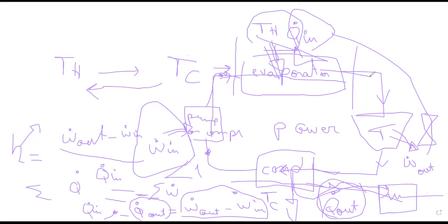And then, after passing by the expansion valve, when it goes through the condenser, it will reject heat to a medium of lower temperature. So I forced heat to go from a hot place to a cool place by imposing work at the pump level, by delivering work in electrical form to my pump or compressor. And why don't we use turbines in this case? Because a turbine will take work out of my system, and here my purpose is not to produce work. My purpose is to transfer heat from hot to cold places.